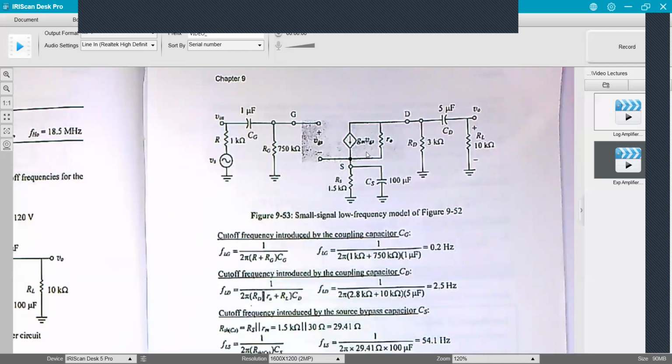That's why I mentioned in the bipolar case, we'll talk about it when we get to the next transistor. Just as we can calculate the impedance of these capacitors and show this one is actually shorted, we can also compute the value of this resistance and see it is so large compared to the rest of these resistor values that we can pretty much ignore it and not even draw it in the circuit.